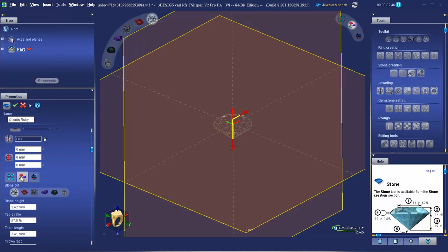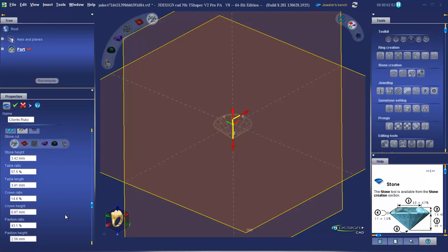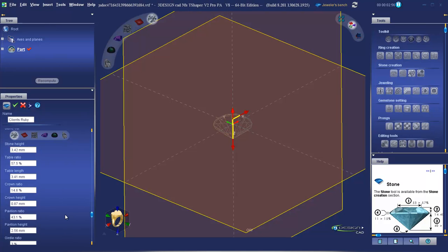Here we have all the cut parameters both in percentage and mil measurement, so you can match the stone you're using to the documentation you have for the stone. Now, you're not going to rapid prototype the stone. This ensures that you make allowances for your stone in the setting. If you've got a thick girdle, you'll know you have enough length on the claws. If the stone has a longer than usual pavilion, you'll know the culet won't be digging straight into the finger.